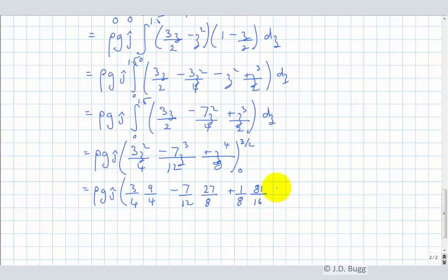So the density we know, 1,000 kilograms per cubic meter. G we know, 9.81 meters per second squared. And of course this is all a number we can evaluate. So we calculate this out, and it comes out to 3,448.8 j Newton meters. Notice there's still a j in there. That's coming from here. And that's what gives us our direction. So that's the moment due to the fluid.